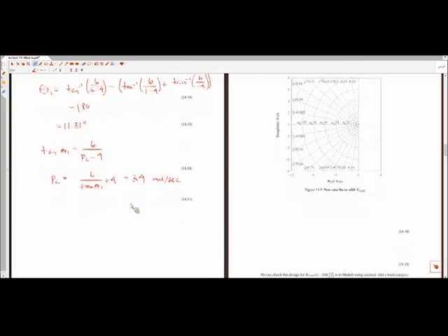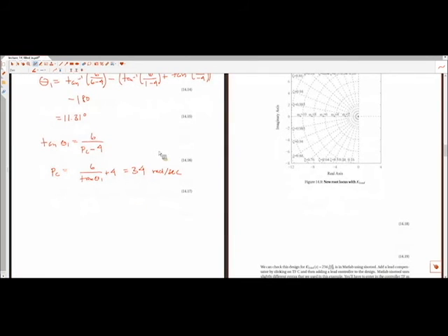Okay, so what this tells us is that our lead controller, we're almost there. Of the 3 variables of our lead controller, we figured out 2 of them. It is designed to be k times s plus 6 over s plus 34. Right. And we'll show on Friday's class how this forced the root locus to go directly through our desired point. And we'll also show how we figure out this unknown k value. Right here, this is still unknown.